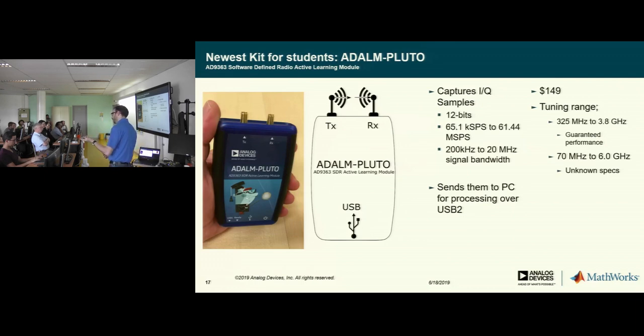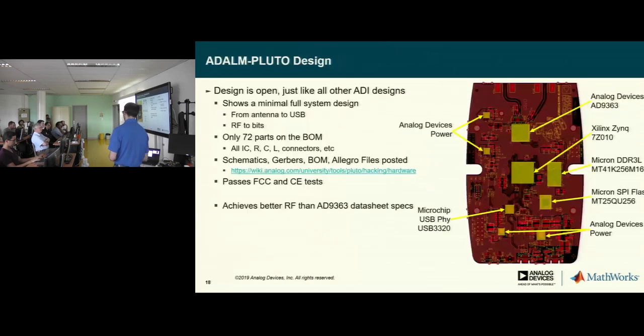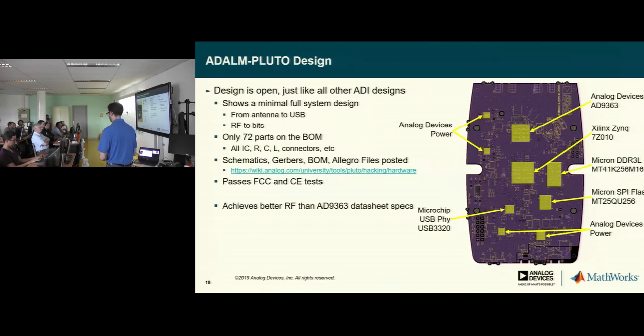Yeah, and if you're, say, pinning out both transmit and receive and both channels for transmit and receive, you actually cannot keep up with it even with USB 3.0. So we say that USB 2 is fine for most people's applications.